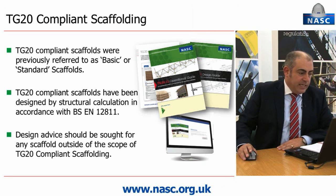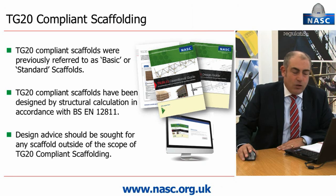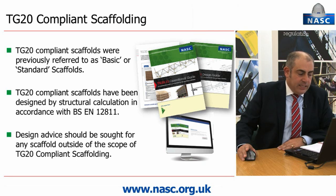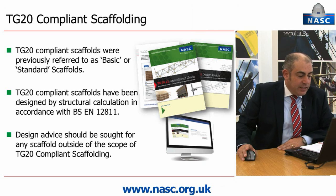TG20 Operational Guide features compliant scaffolding. TG20 compliant scaffolds were previously referred to as basic or standard scaffolds. They've been designed, as mentioned earlier, by structural calculation in accordance with the British and European standard 12811. Any scaffold that falls outside of the scope of a TG20 compliant scaffold should be designed as a bespoke scaffold.